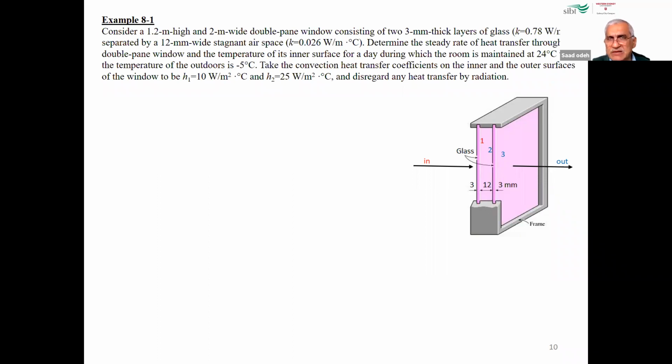If you see, let's say a building, all the building covered with windows, then definitely they have used double glazed window, because if you put the whole walls glazed, there is no brick, only, let's say, steel structure, and then you cover the gap by windows, then if you don't use double glaze, then you have a lot of heat loss and heat gain.